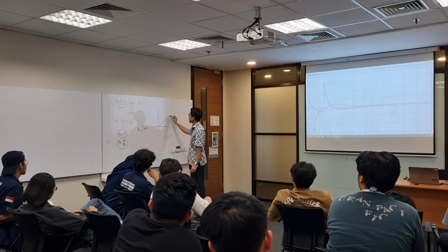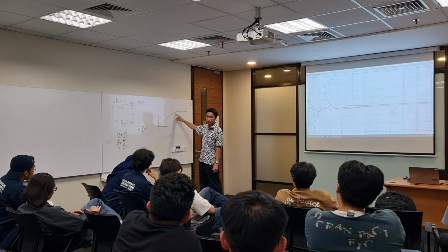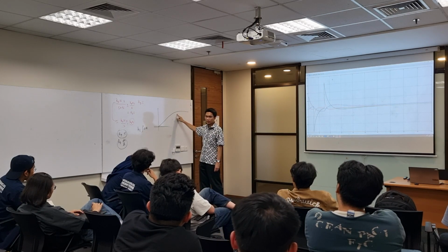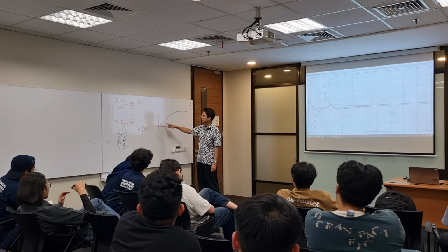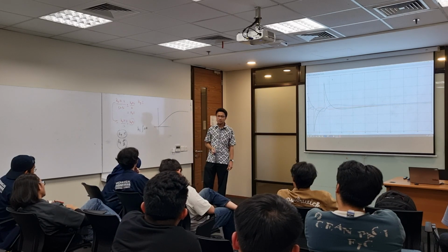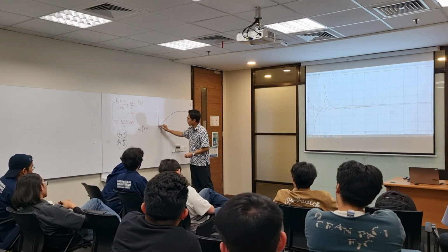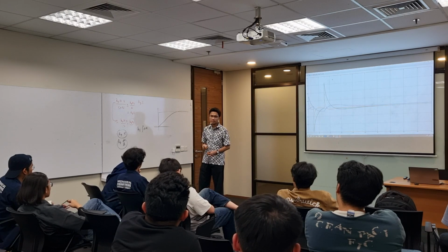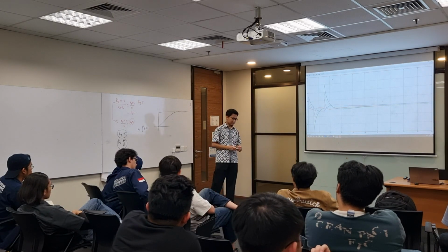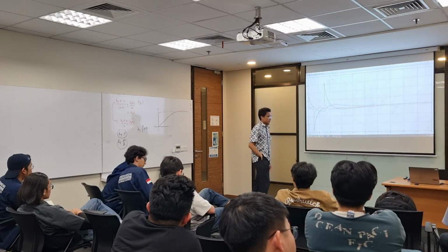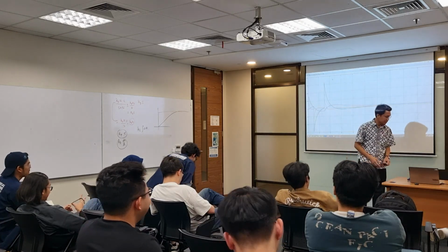If you have a ramp like this as your desired value, then the derivative control is not really helping, because the derivative of the error, with this kind of desired value, is not large compared to having a step input like this, a sudden change. Yes.